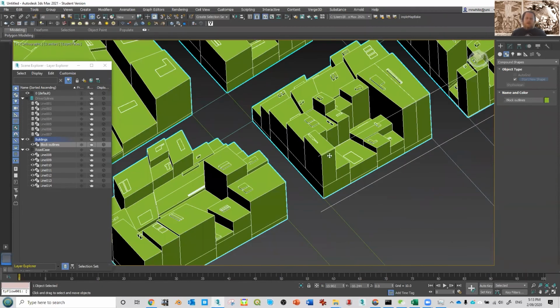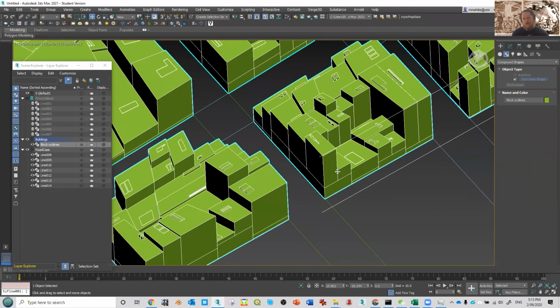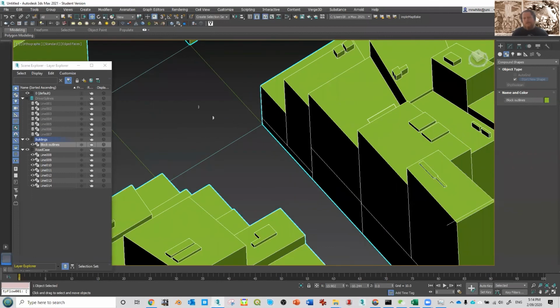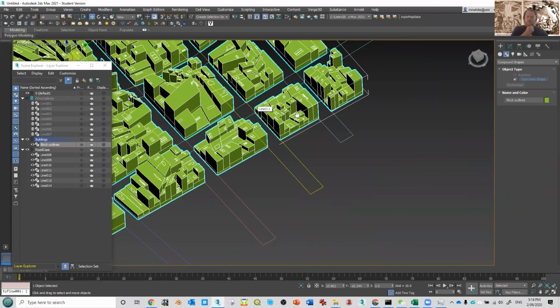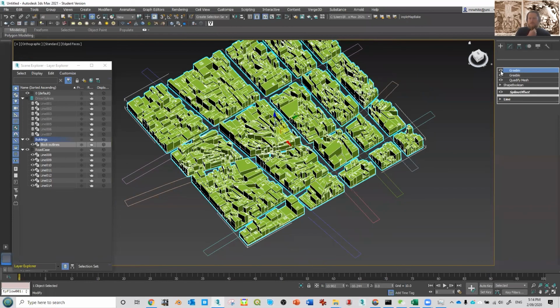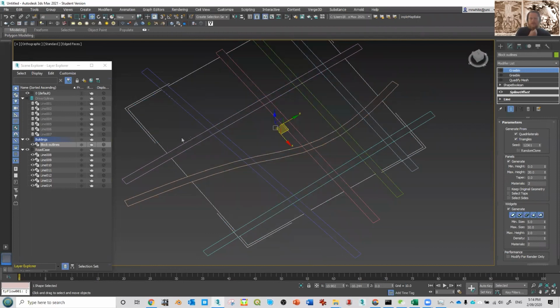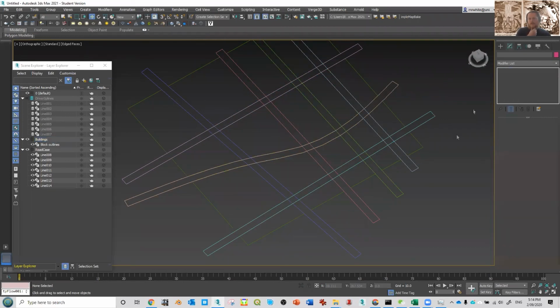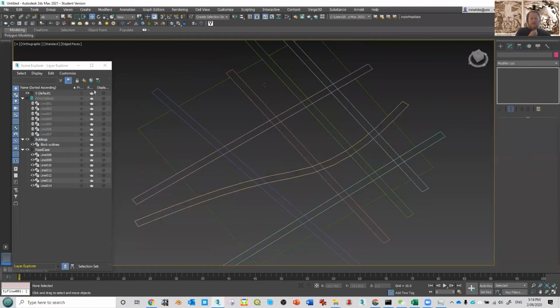I could copy that as a reference, apply that stuff, and then take that same shape and loft or sweep a footpath around it. But that would give me a sharp corner, and I want a bit of a radius here. So what I'll do is turn this off, back to my nice rectangular shape, and draw another rectangle.